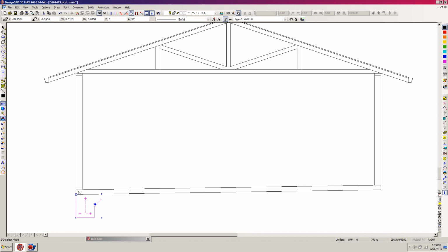And I can mirror that symbol by hitting the mirror command, which is the slash command, but it's got to be selected to do it. So I'm going to select it. I still want to reset my handle to this point here, hit the slash, which is mirror, and go to the other side. And now these aren't quite level, so what I'm going to do is explode both of these and hit this explode, selection explode command, and the same thing with this one. I'm going to hit selection explode command.